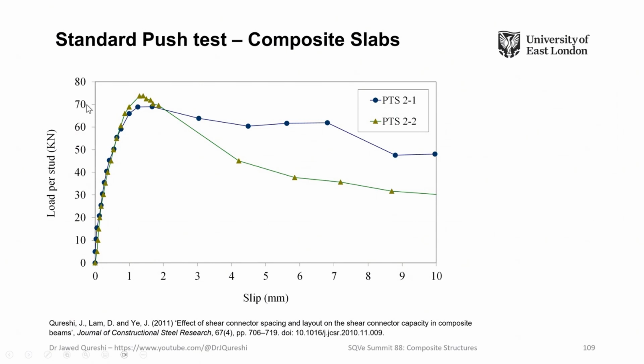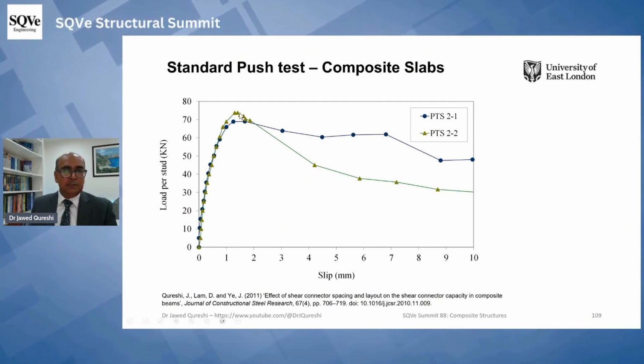You can see here that stud strength is about 70%. In design codes, what they do is that they carry out lots of testing, and they figure out what is shear stud strength, and they apply partial factors, and after applying partial factors it comes out to be about 55 something. So that's how they do it in design codes.